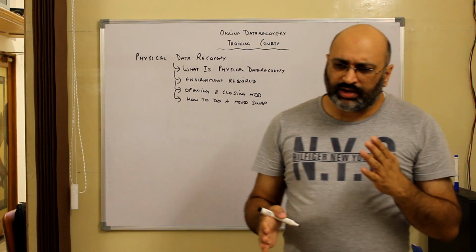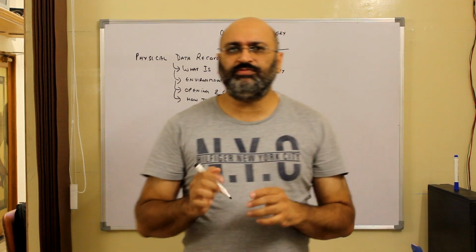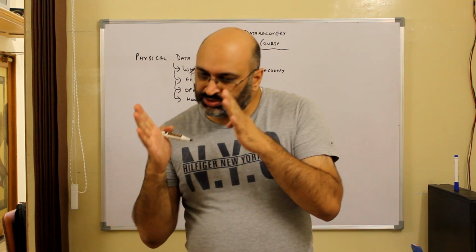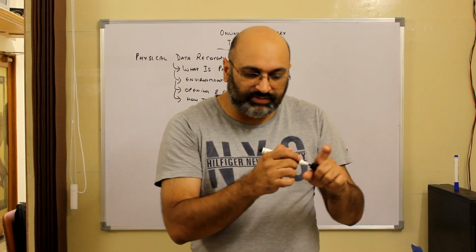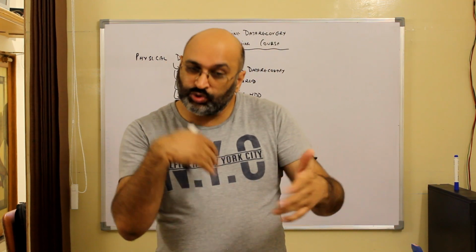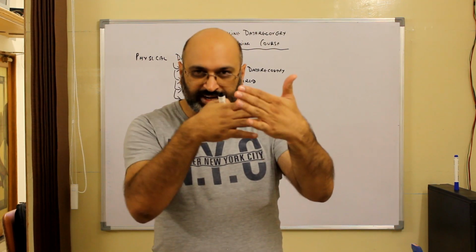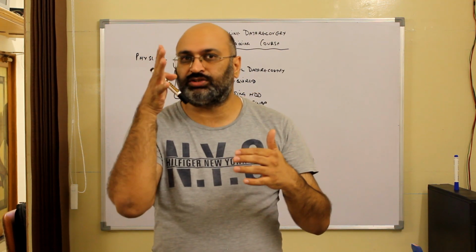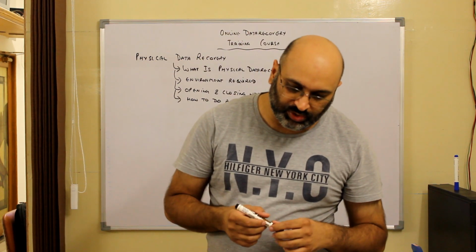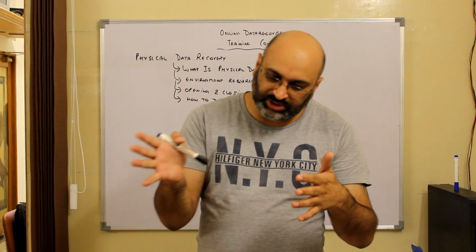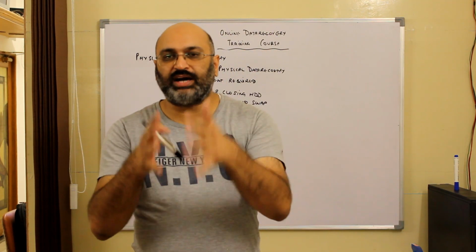There are many different varieties of hard drives. So I will prepare some videos in which we are doing job work on different hard drives, and every different hard drive will have its own method of changing the heads. Some of the hard drives are ramp based models. The head is parked outside the platter on a plastic parking area called the ramp, and in some of the hard drives the head actually goes inside the platter and near the main rotating motor where it parks itself.